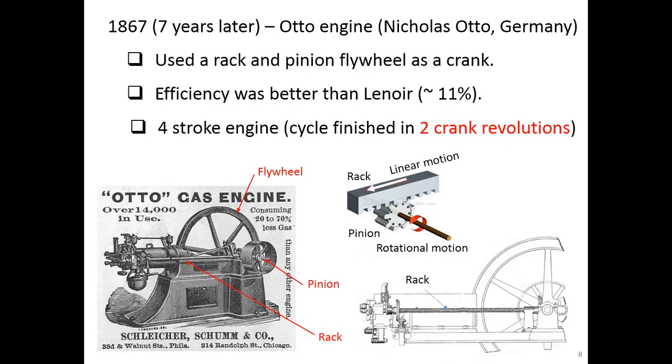So in order to keep rotating through that other round, they need power, and this flywheel is used to provide the power to that round in which no power cycle happens. This happens in present engines also. Every engine needs a flywheel in order to provide the power for the 1 round of revolution in which no power is produced.